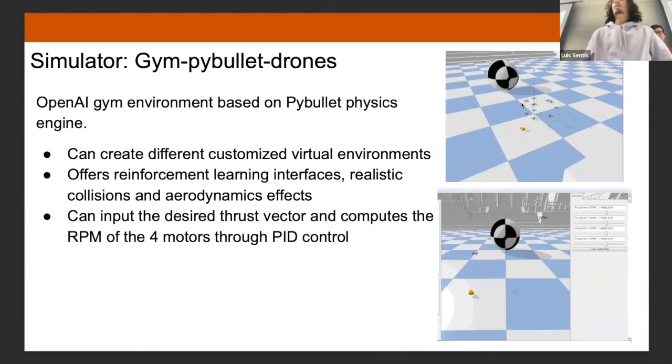Yeah, so the way we actually went about running this was in a simulator called Gym PyBullet Drones. Pretty much what this is, is an OpenAI gym environment, and it's based on this physics engine called PyBullet. So it allows everything to be just run in Python, which is pretty nice. A lot of well-known drone simulators like AirSim are in C++. And so for us, we felt it'd be easier to use this specific environment. What was also nice about this environment is that they're kind of like baseline virtual environments that we can customize, that we can build custom environments off of, as well as incorporations of well-known reinforcement learning packages, also some collision physics going on there, and aerodynamic effects are modeled a lot better than some other packages.